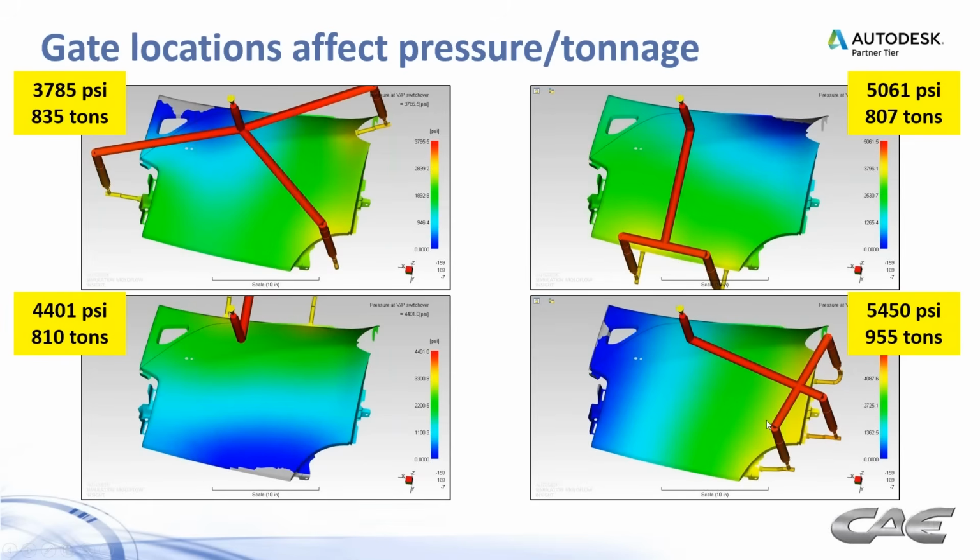So this is still very much within the processing range. It's not difficult to process, but there are going to be those times when you get into a situation with, say, a very thin-walled part and maybe a polycarbonate material that tends to drive your pressures up. And in those cases, you have to really pay attention to where you are with those process settings when you're able to reduce the warpage. So keep that in mind as you go through projects like that.